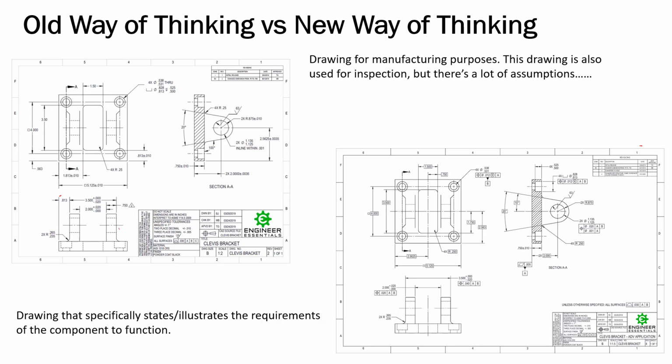I have taken parts that have complex profile on them and put them on a Bridgeport with a digital readout and used that to find my points. What I wound up having to do is go back into the CAD model, get these points, which are basic dimensions, and put a table on the inspection plan and say, okay, if you can set it up with this being X and this being Y, secured down, and in Z, hopefully representing the datum reference frame, then we can take an edge finder or a probe and run out to these absolute points and touch off, and we know a range of where we have to be on that profile.